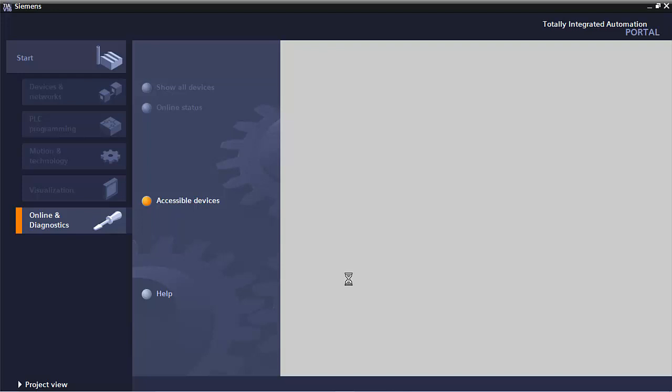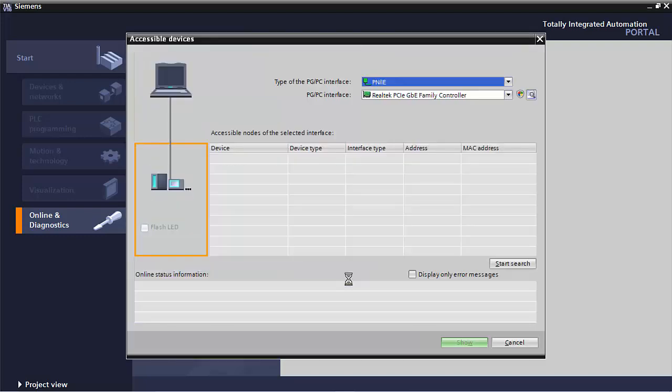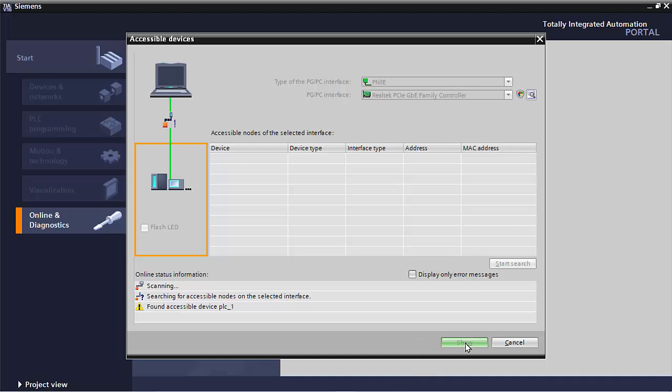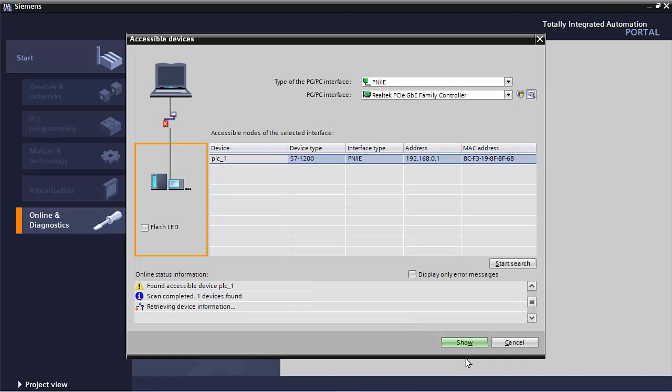An FC block is basically used in programs where data does not need to be stored, and an FB block is used where data needs to be stored. In some cases, when power is switched on and off, functions in control need to retain or non-retain data, which we would like to show.